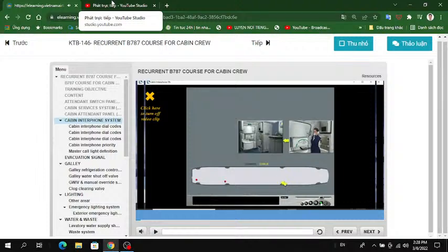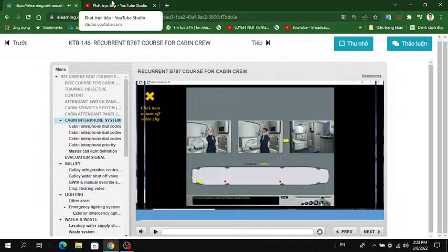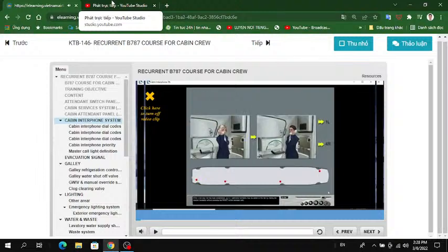A call to another cabin handset may be remotely answered. To remote answer, enter the dial code of the station being called. A call may be transferred to another cabin handset by dialing that handset. After a two-way call has been established, up to two additional handsets may be added to the call by dialing the desired handsets without pressing the reset button between calls.